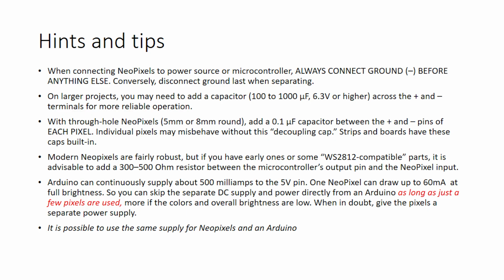You'll get away with a few NeoPixels. Well, you just saw me driving 16 of them in a ring out of an Arduino. But then I had the wick turned down to 10 or 15 on them to try and get the exposure to work. If I tried to run that full blast, it would probably blow that Arduino's pins. You know, you can get 60 milliamps on a single LED here, so you have to be really careful about it.